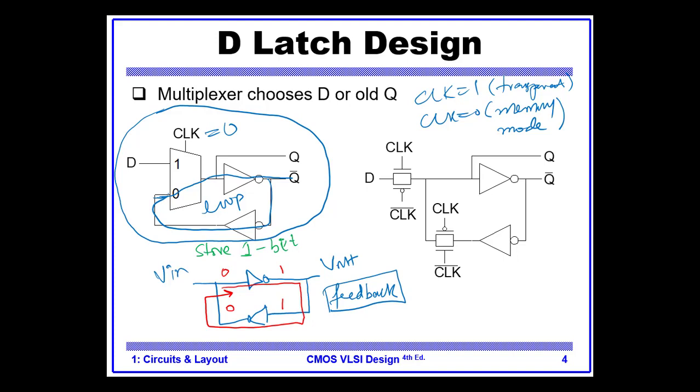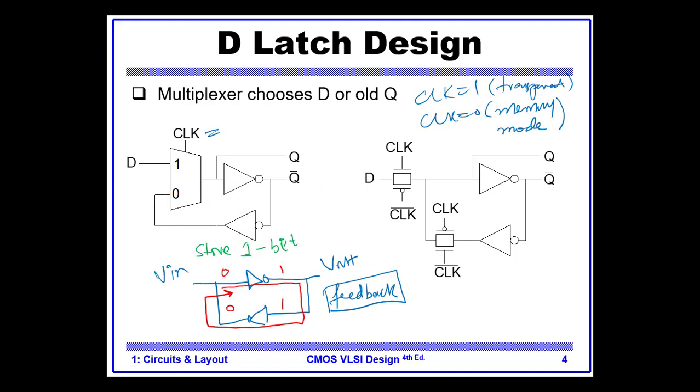What is the difference between this circuit and the circuit which was consisting of 2 NOT gates? The difference is that it has this clock signal, it has control. So it has the control signal. The control means that you can choose when to change the latch from memory mode to transparent mode. So it was the circuit number 1.